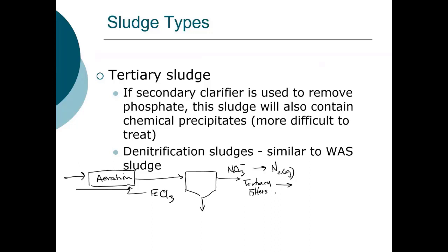Do we have any additional residuals from this process? That'd be the concentrate from the tertiary filters. So the tertiary, they would be if they were membrane filters, and I should have explained, these are actually sand filters, so they're gravity, but you're onto it. Backwash from sand filters. The backwash.